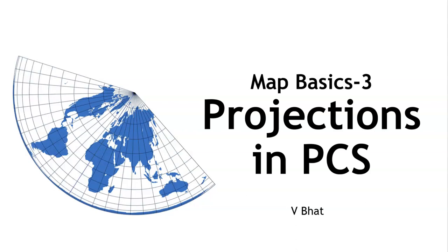Hello everyone. In this session, the objective is to describe the conceptual backgrounds of projections which are used in the projected coordinate system, or the so-called planar coordinate system. Previously, we noted that the Earth is really big. Not only is it big, but it is a big round spherical shape called a spheroid. A globe is a very common and very good representation of the three-dimensional spheroid Earth.